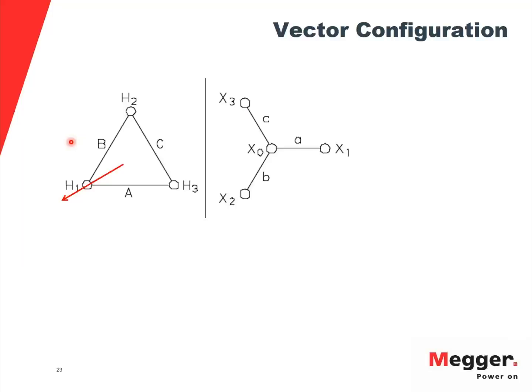And what we're doing is we're looking at this, and then we're going to compare our second vector diagram. So remember, this is a Dyn transformer. And so when you see something, the D will be a capital D, meaning it's a delta on the primary side. And then it'll be a lowercase y, meaning that it's a Y on the secondary side. And then it'll also have a lowercase n, meaning there's an accessible neutral.